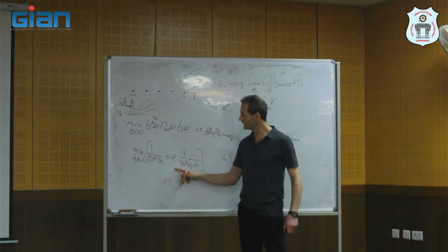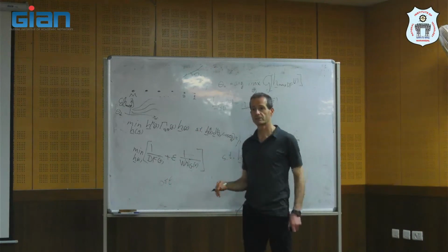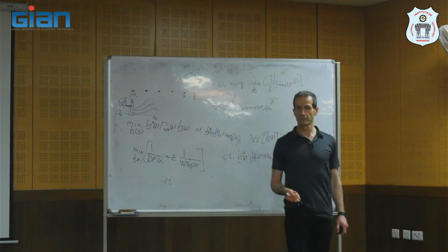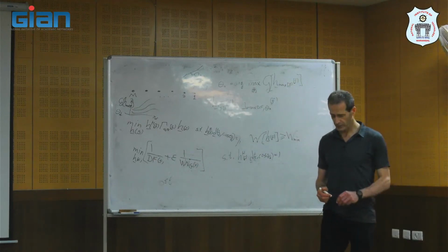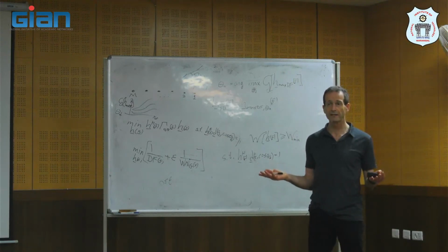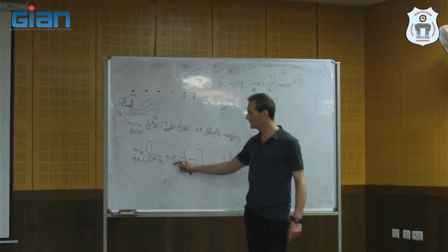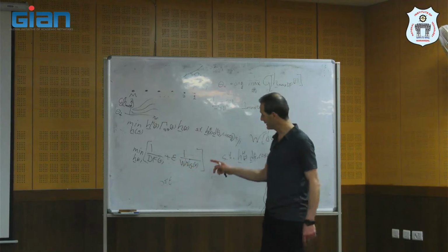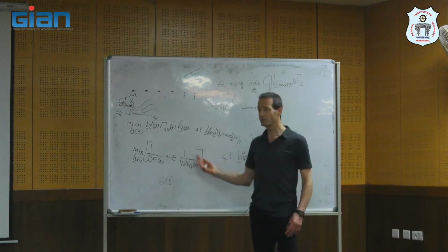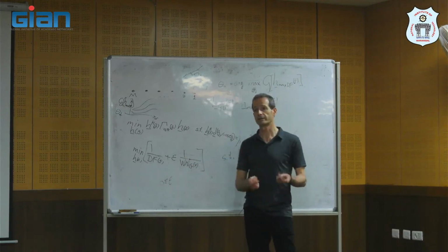So epsilon is like a trade-off parameter to control between white noise gain and directivity factor. By the way, whenever you have a trade-off between two things, you can add a parameter. If I have three things, I can add another parameter. And the parameters control how much weight.